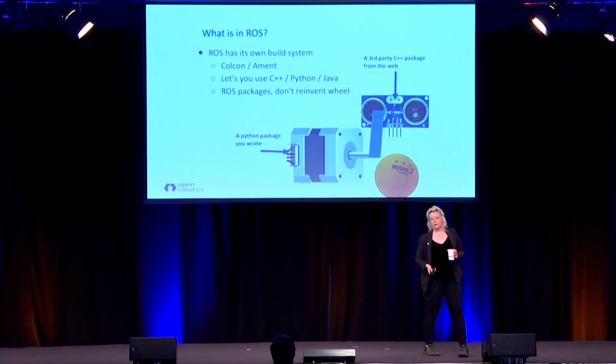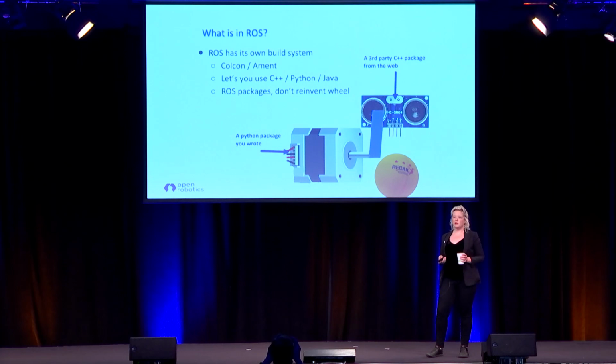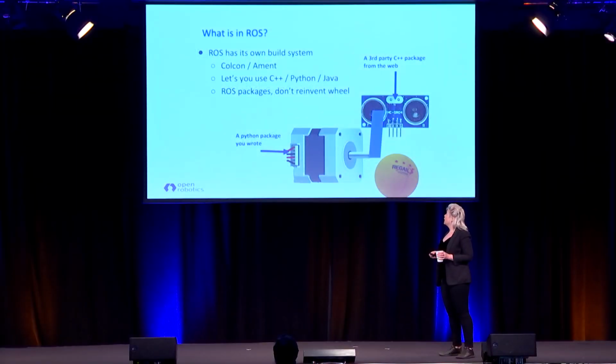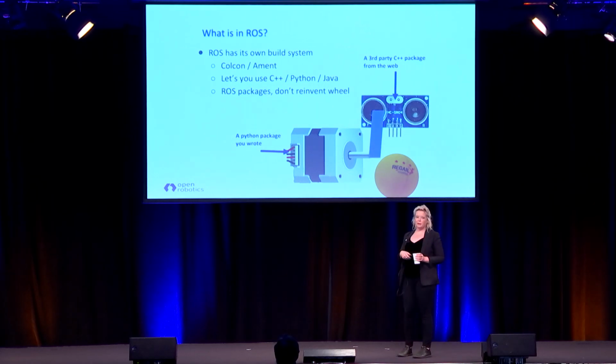So one of the biggest parts of ROS, and one of the more useful parts of it, is that it's a sort of federated build system. In the past few years, software has been more focused on these large, monolithic pieces of code. Well, we don't do that because we're an open source organization, and we're working with lots of different people in lots of different places. So we have lots of different repositories. Some of them are C++, some of them are Python, some of them are even Java, which is rough, but you know, it happens. So there's all these packages, and ROS has a build system that allows you to write in whatever language you want. ROS will find that package, pull down latest versions, compile them, and build an executable file that you can run.